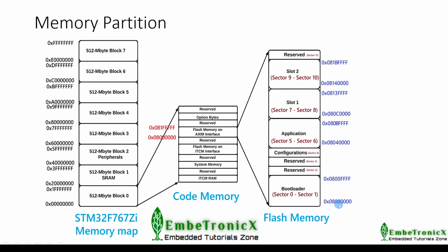We are placing our bootloader code into 0x08000000 and the controller starts from 0x00200000 because in the boot mode I told you that if the boot pin is 0, then it will start from 0x00200000. Actually, both are pointing to the same memory. The only difference is the bus that is used to access that memory.